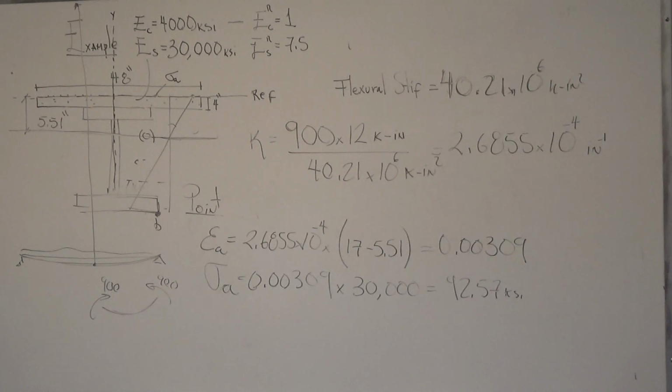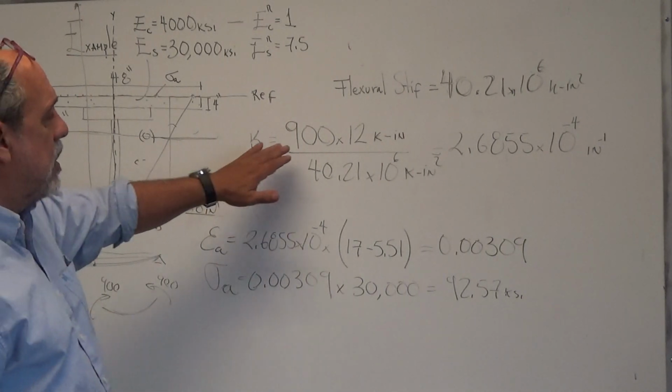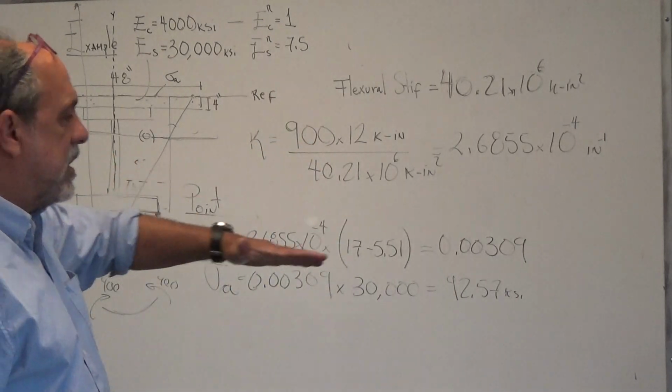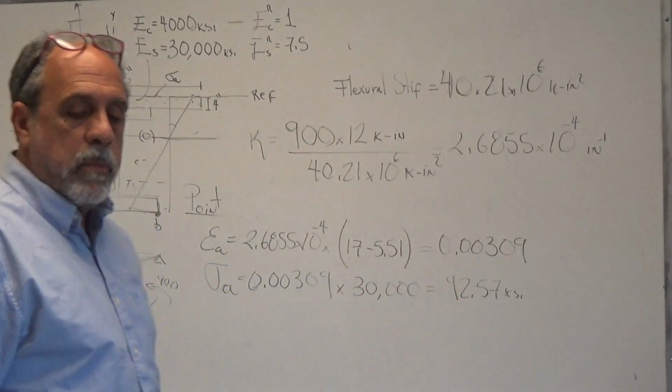You know, the stresses that we can normally accept on steel beams under loads like that would be on the order of 20, 25 at the most, something like that. So basically ksi. So we've got maybe a beam that is too small or loads that are 4 times too large, or a span, whatever it is that you need to do to reduce that moment. Or another way to say it is that the moment that we can really take is not really 900, but something more on the order of a quarter of that. So this stress would go down to about a quarter of that.